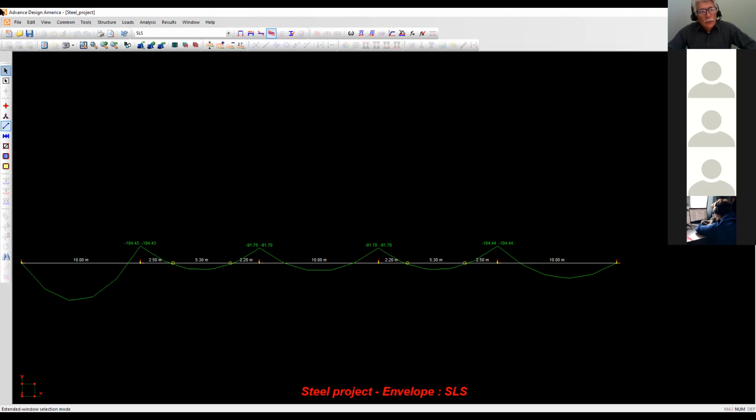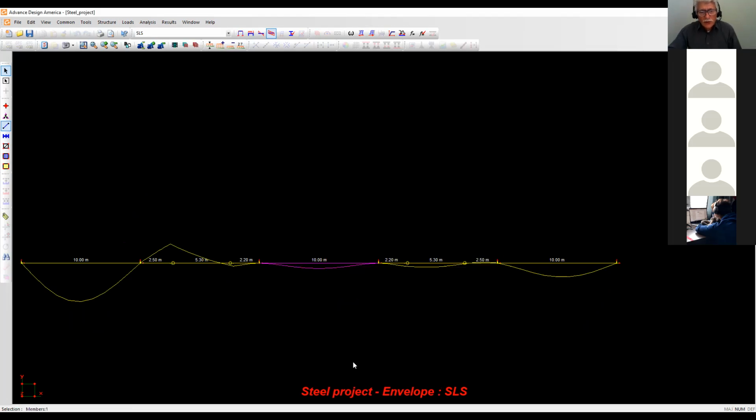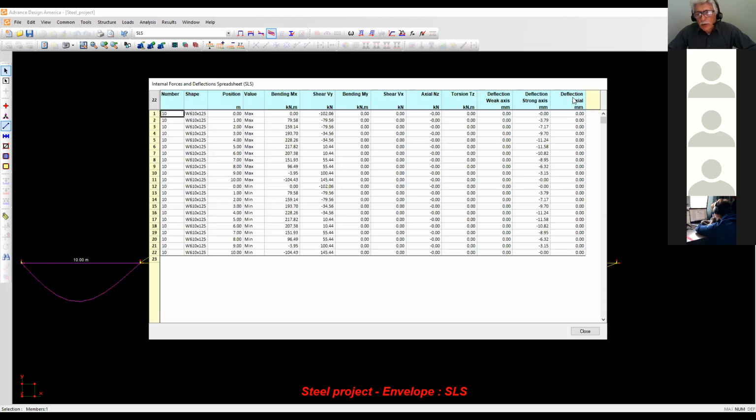So what I'm going to do now. I'm sorry, no, these are still the moments. Hold on a second. The deflection. So I take this off, okay? And I do deflections about the strong axis. Perfect. Press apply, and here are your deflections, okay? Now, if you want to go see the deflection here, you can click here, and it's going to tell you what the deflection is, okay, about the strong axis.